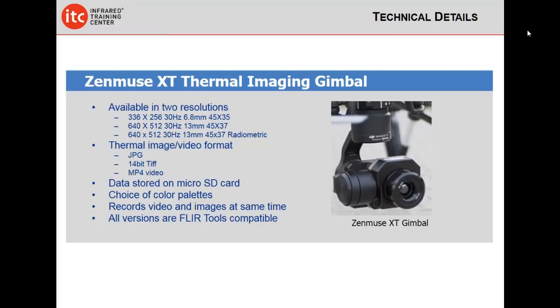They both measure. Well, the difference between the two is the XT performance line will only allow you to measure a spot radiometer. So you'll have one measurement spot. The radiometric version means that each pixel contains temperature. This allows us to use a measurement box tool to give us average, highest temperature, or lowest temperature. And the reason behind this, because the pixels actually measure the temperature of the image radiometrically.